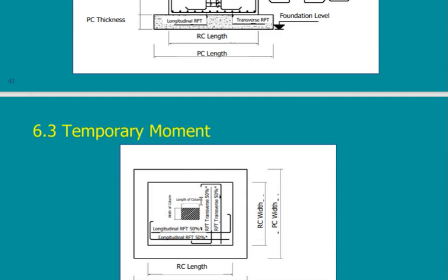But if I go to the middle, say a little bit to the right and a little bit to the left, then I don't need the 10, I may need 5 or even less. So I make something called curtailment. Curtailment means that I do not extend the full amount of steel from the edge to the edge.